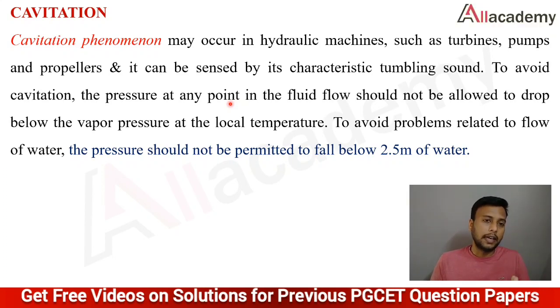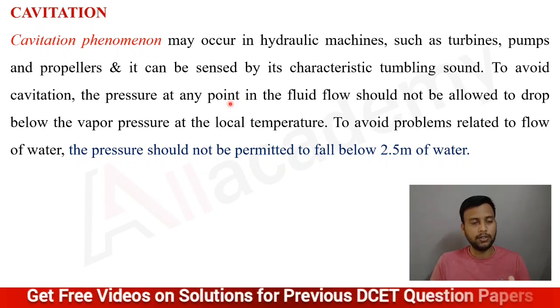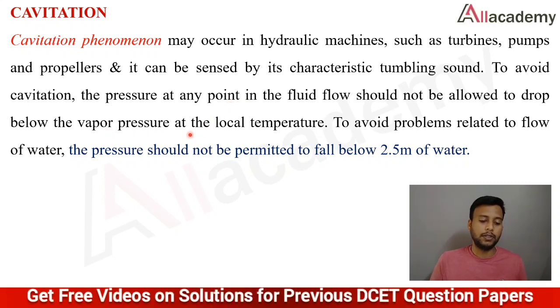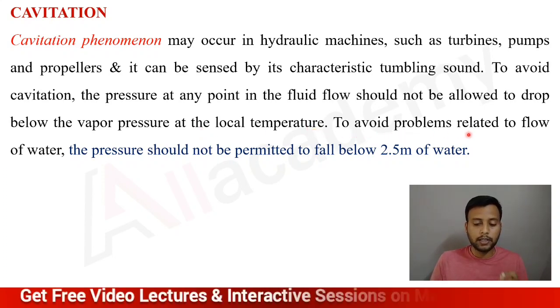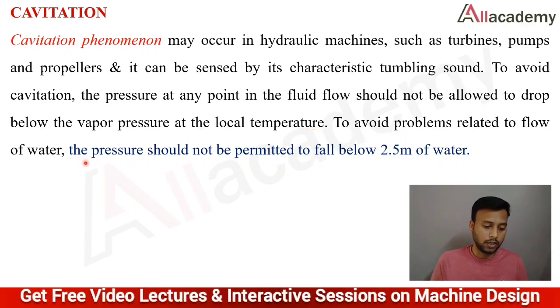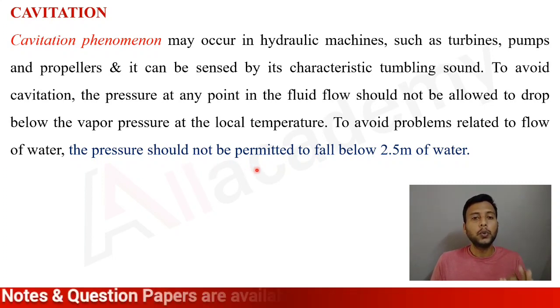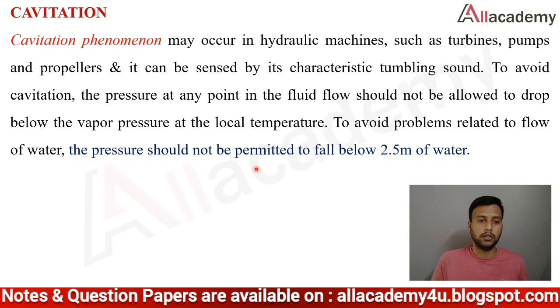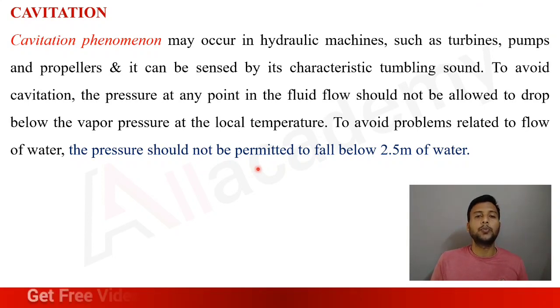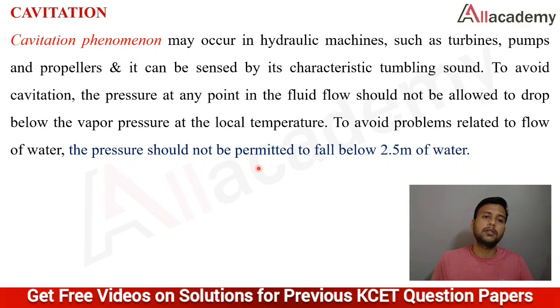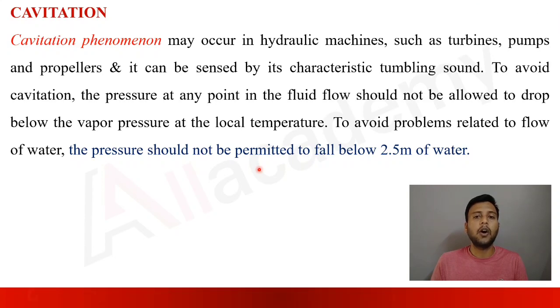So we need to take care that the fluid flow at any point should not drop its pressure below the vapor pressure at any local temperature. One more thing: to avoid the problems related to the flow of water, the pressure should not be permitted to fall below 2.5 meters of water. If it falls below 2.5 meters, obviously the cavitation process will start, and the phenomenon will be observed.